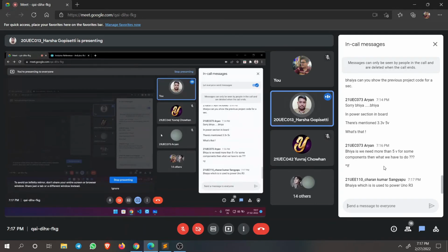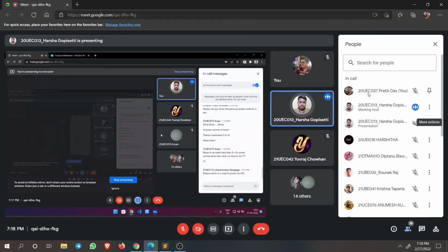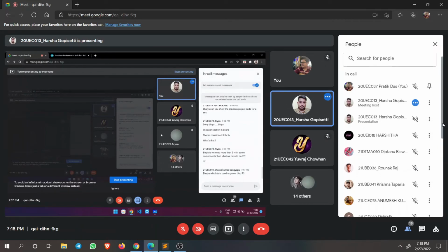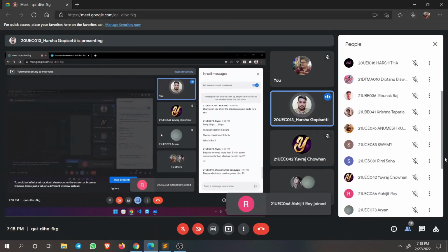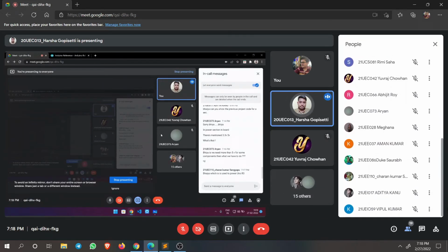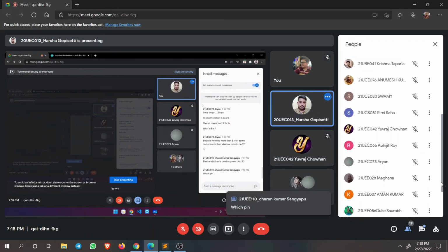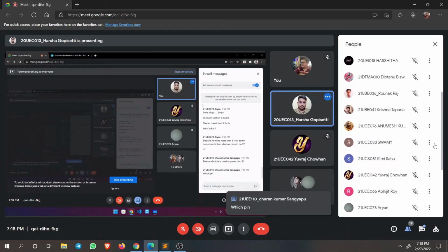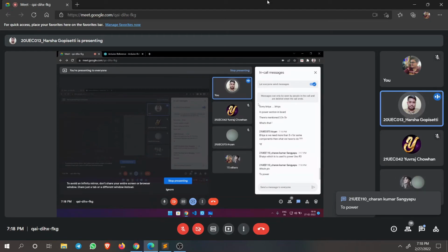Whenever you have a motor, the motor speed can be controlled by controlling the voltages at its terminals. It will have some threshold voltage. Below that it won't work. There will be a voltage where it works. From that voltage to some voltage, there will be a specification, somewhat like 0 to 9. If we assume 0 to 9, we can control speed by controlling the voltage.